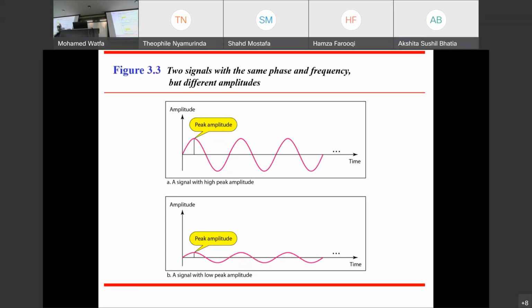So one more time. Amplitude is the height. From here to here, that's called amplitude. Typically the peak amplitude. That's what we care about most. And frequency is how many cycles per second. And period is the reciprocal of my frequency, which is 1 over it. So if my example had 3 cycles per second, so 3 hertz, what would the period be? 1 over 3. What's the unit of period? Second. Very good. So period is time. Frequency is cycles per time.